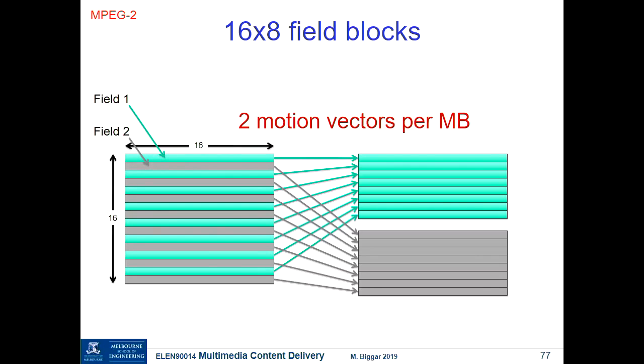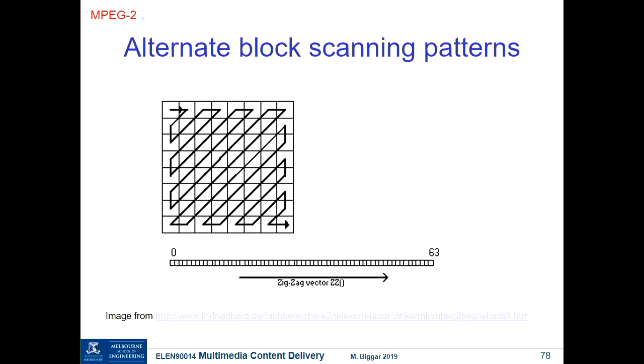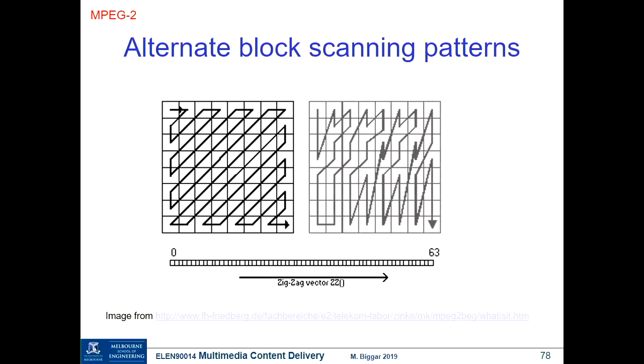Yeah. And so for that reason, when the MPEG group was defining MPEG-2, they allowed for an alternate scanning pattern, which looks kind of crazy, but if you take a moment to see what it's doing, it's just putting more emphasis on these vertical high frequencies, so they're scanned out a little bit earlier than the other ones. Again, of course, I don't want you to reproduce that.